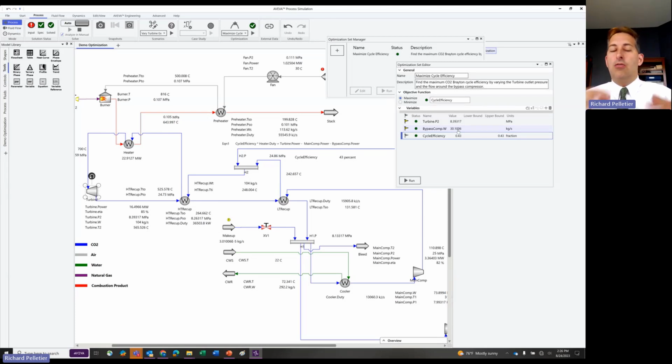This isn't the overall optimal, because if I loosened this constraint and didn't have this upper bound, it would solve to 0.45. But because I've imposed this upper bound, it limits the solution. And we can put these bounds in for any and all variables in this list, whether they're manipulated or they're just being reported back to you here in the file. So now I don't have the upper bound. If I run it again, you can see, oh, it gave a different solution.